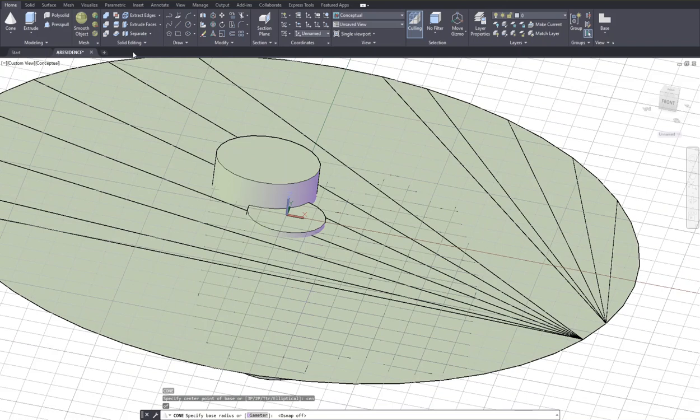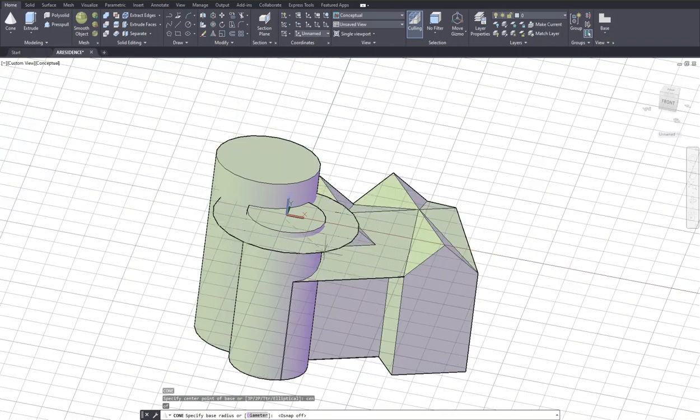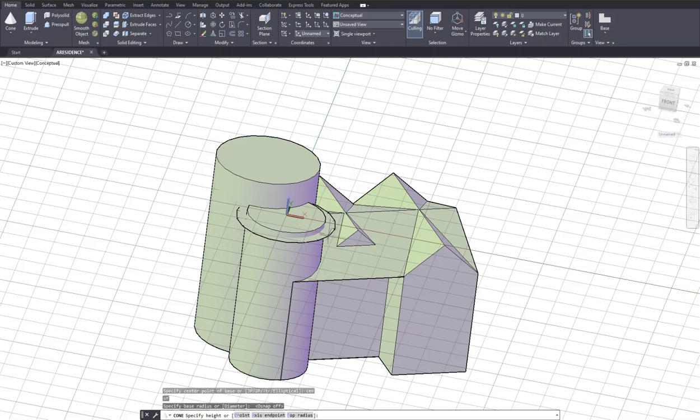Okay, so we're going to continue from here. And I am going to make this cone, the eave, extending out about... I turned off the object snap. I am extending the eaves of the roof about 3 feet. This is about 3 feet, and I move my cursor up to a certain height, and click on it.